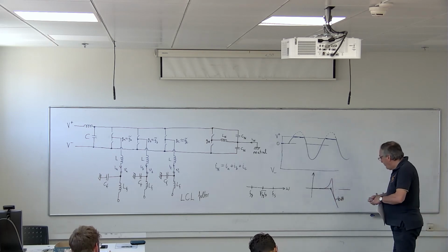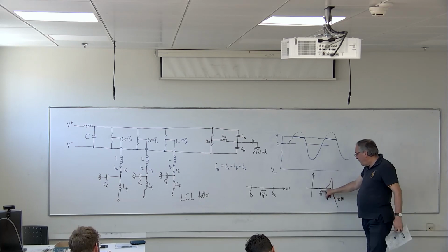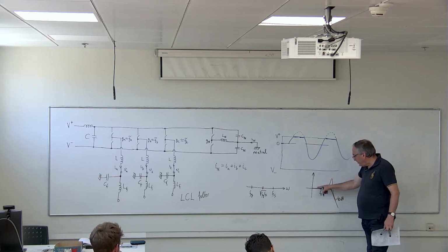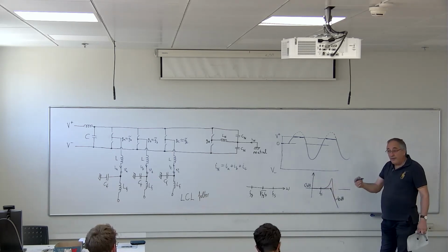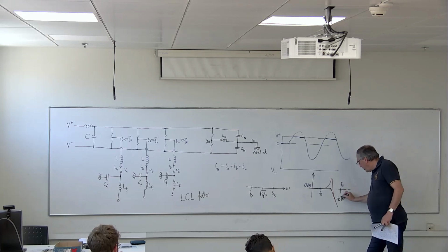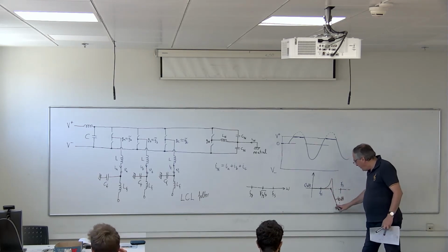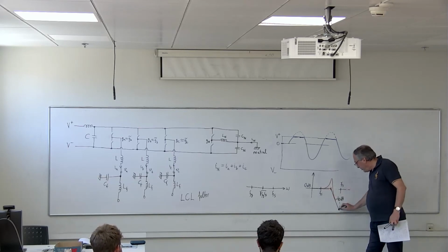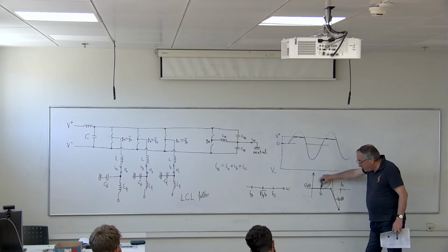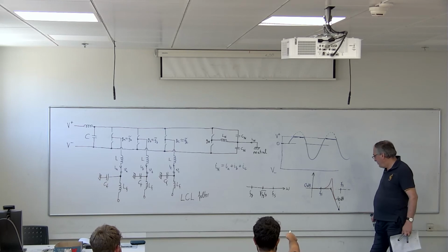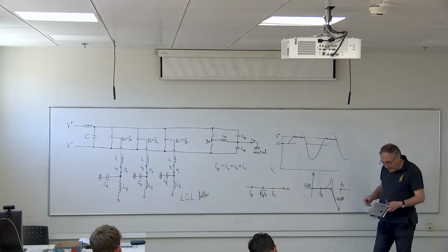You want your low frequency signal, FG, to pass unhindered through the filter, so that you are in this region where the signal passes unhindered. This is 0 dB. And you want the switching frequency, which is here, Fs, to be strongly damped, strongly suppressed. So you see here, you have a very low level for the transfer function, which means that this is strongly suppressed. So you want the resonant frequency to be between the useful frequency and the switching frequency. That is FG. Oh, I'm sorry, this is Fs. Yes, Fs. Okay.